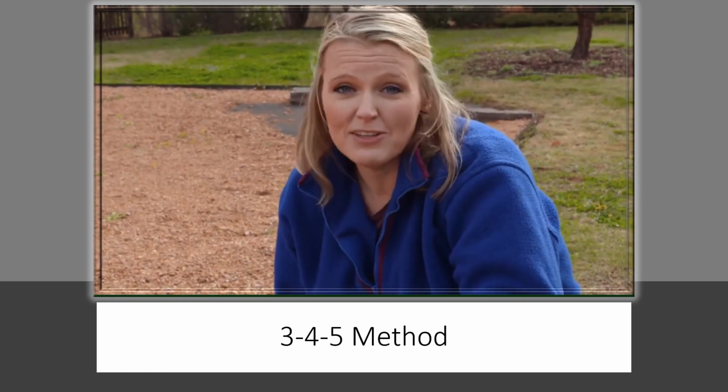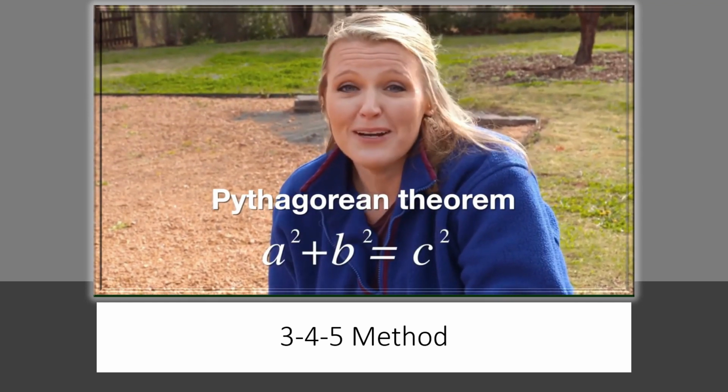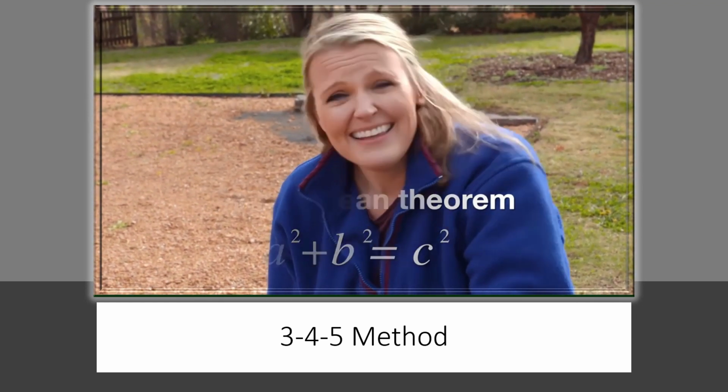Now this is called the 3-4-5 method. You could actually double those numbers and make it the 6-8-10 method if you were building something larger and wanted to have better accuracy. Really, this is using the Pythagorean theorem. You might remember a squared plus b squared equals c squared. I think I might owe my math teacher an apology because I told her I'd never need to know this in real life.